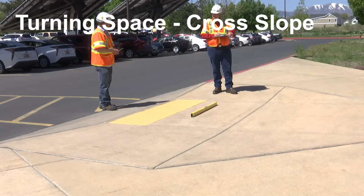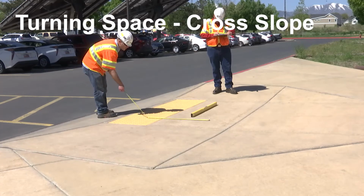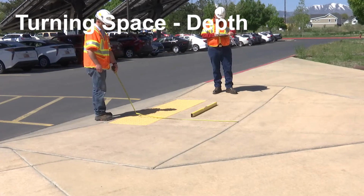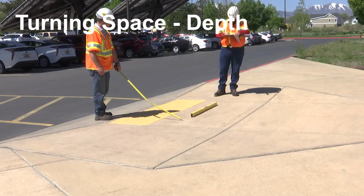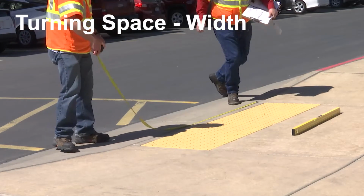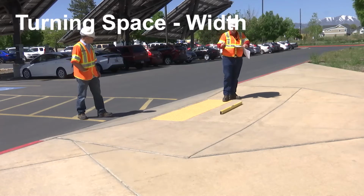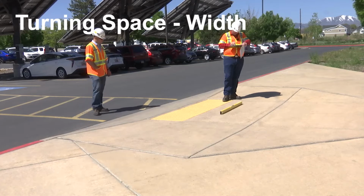Cross slope of the turning space is 0.1%. The depth is 5 feet 9 inches, which is greater than 4, so we pass there. It's 8 feet for the width. And then you check to make sure that there aren't any grade breaks, and I do not see any grade breaks within the turning space, so we pass there.